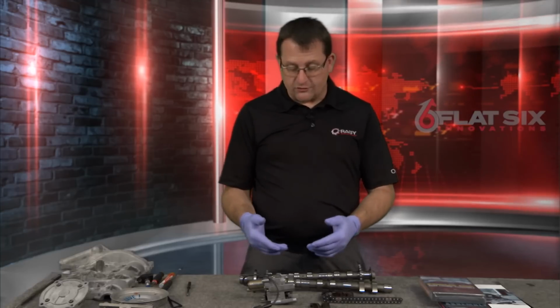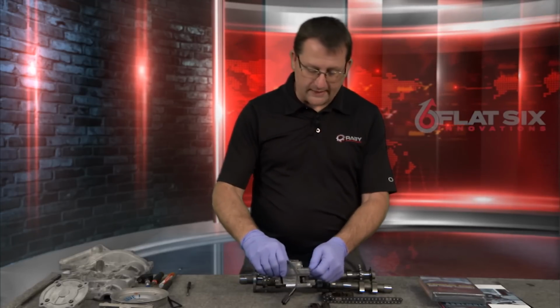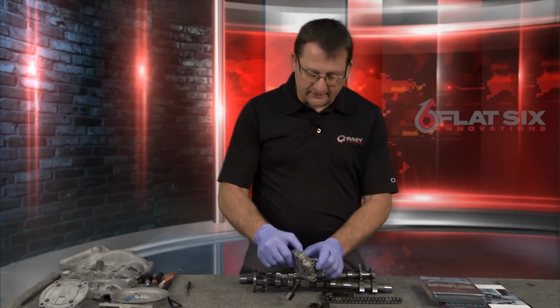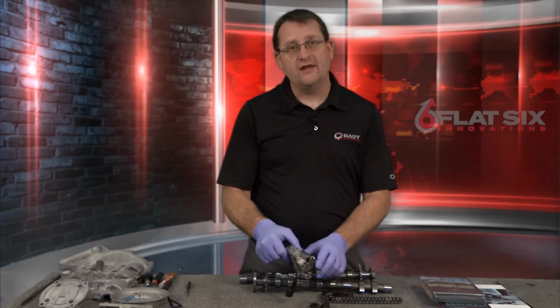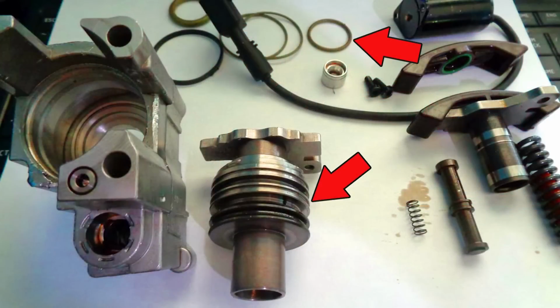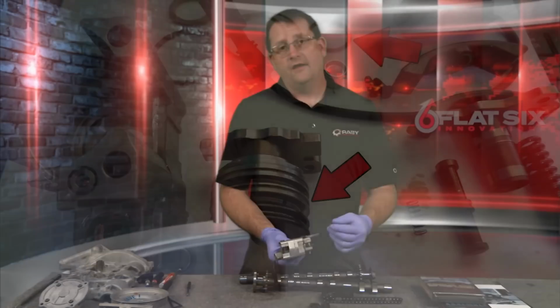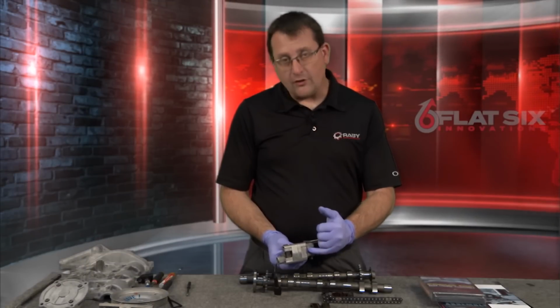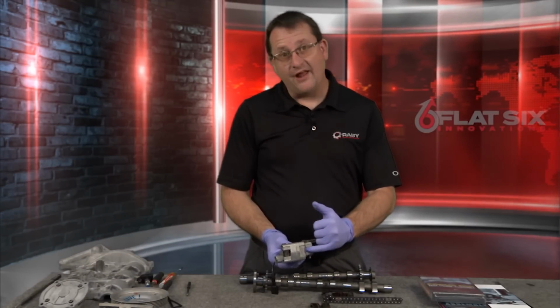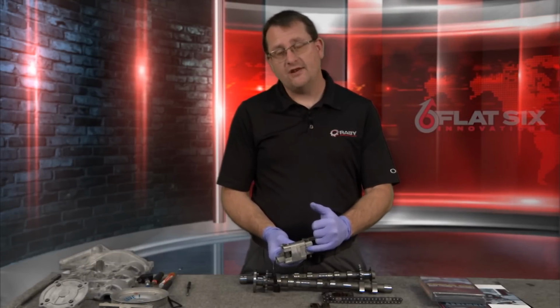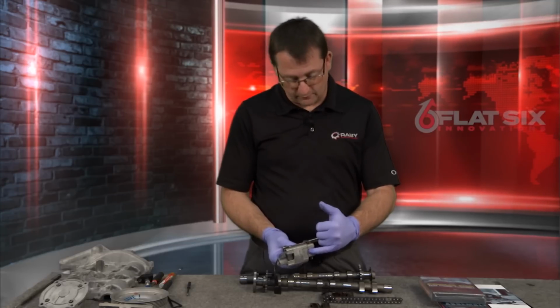You want to make sure that you don't have any green type material sticking out of this chain adjuster, okay? The inside of the chain adjuster is some green material, and that can actually start to rupture and fail. So if you find this mint green type of material in the oil or in the sump or sticking out of here, that tells you that you've got a chain adjuster that is starting to fail, okay?